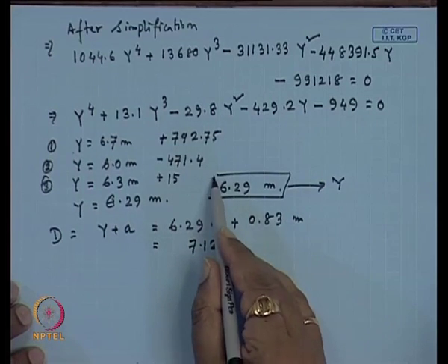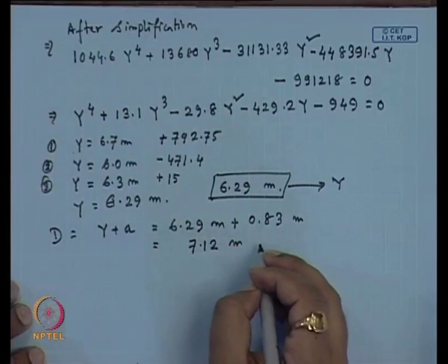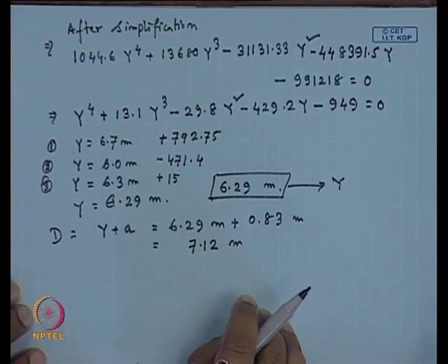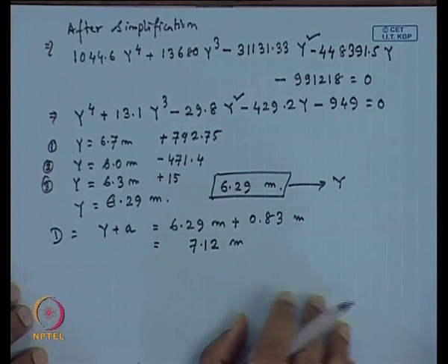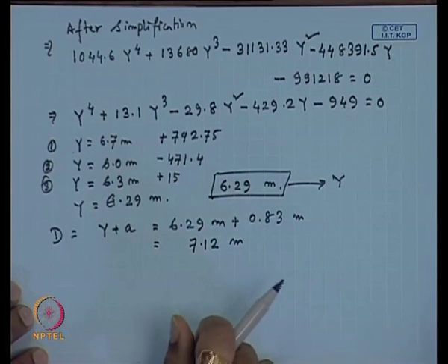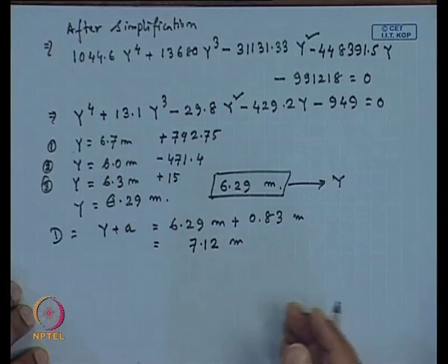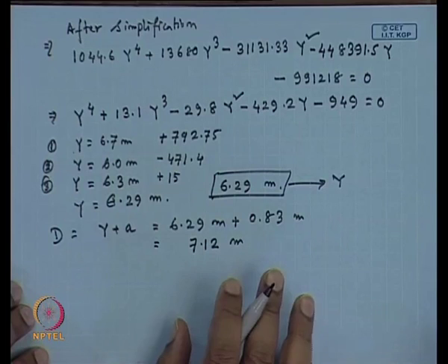Now, here also once we get the y value, then we can determine the value of z, and then we can determine the value of P p 2 b or P p 1 b, that means the stresses at different levels. Then, once we put this value, we can check by taking the summation of all the horizontal forces, whether it is getting close to 0 or not.